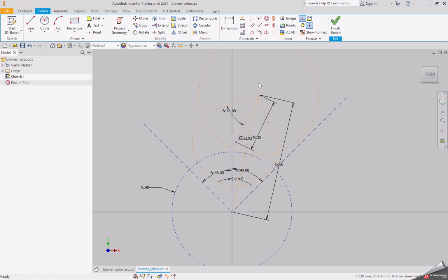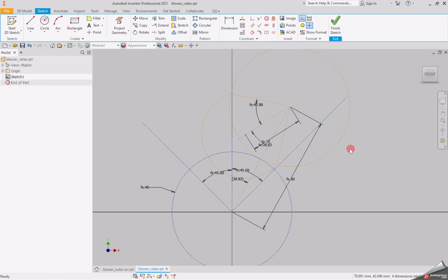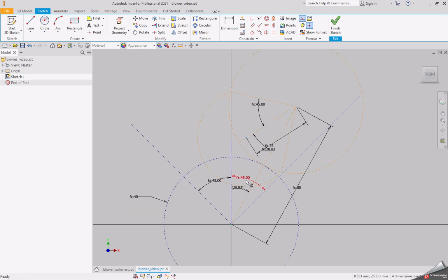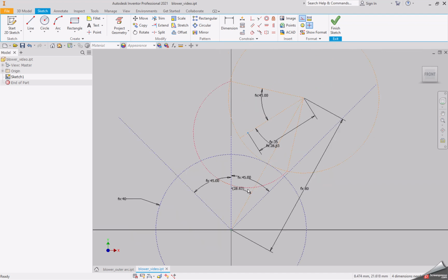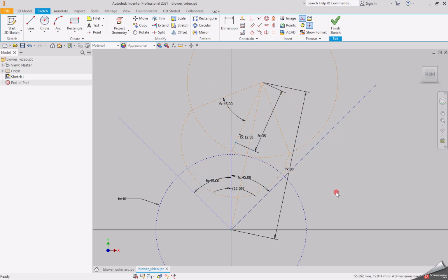what we need to establish is the geometry of this rotation from 0 to 45 degrees, because the rest will be either symmetric or mirror. So what we are now looking for is the curve that is basically produced by the tangent to this lobe going through a contact point. So where will be the contact point? Well, the contact point is kind of tricky